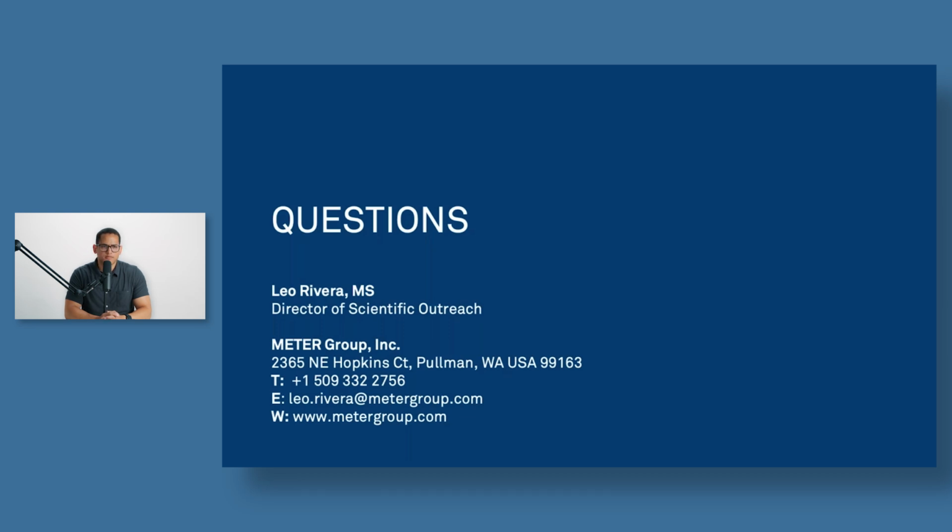I've got a couple on field measurement best practices. So one of the suggestions or best practices when it comes to installing TEROS 21 water potential sensors is to pack the native soil around the sensor before installing it. The question is, how does that work with these deeper installations, like we mentioned before, when they're multiple meters down, maybe even 7 to 10 or so?